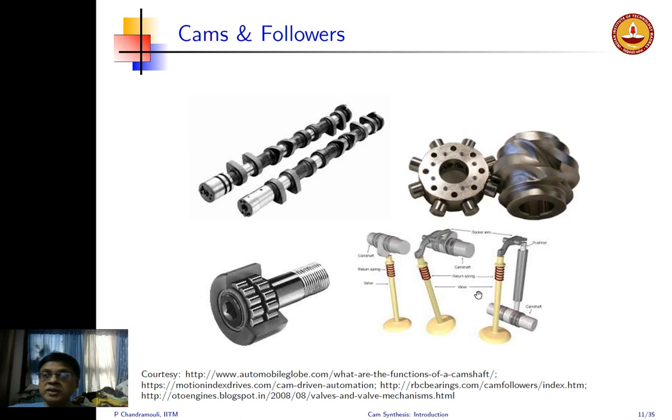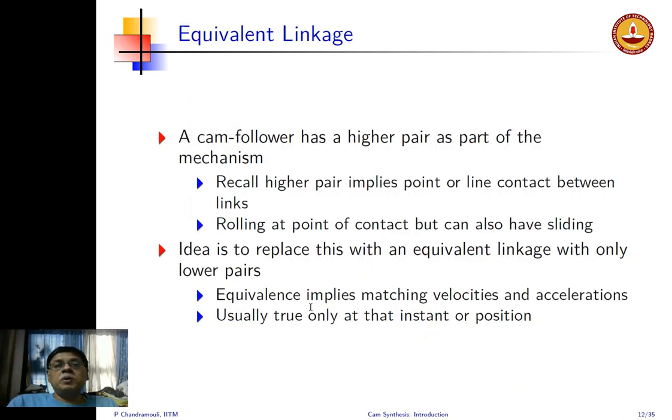You have a direct overhead drive, and this is another configuration where you can have the valve being opened through a separate push rod mechanism here. So this is only a rocker arm. You have a push rod mechanism with a rocker arm here. So the push rod rocker arm kind of design is an old design. Today you will see more of the direct design that is out here. All right, so some pictures just to get you familiar with what a cam and a follower looks like.